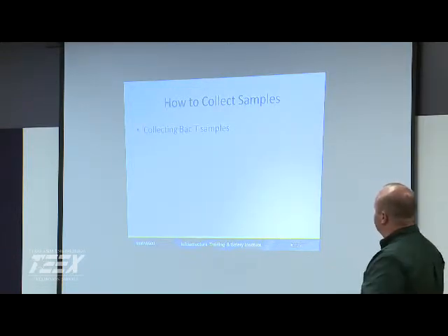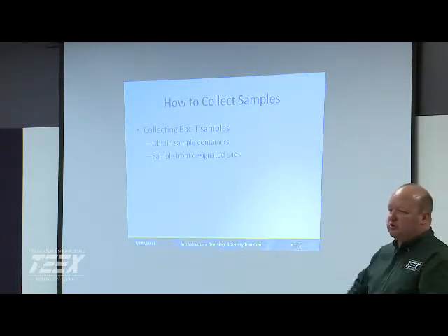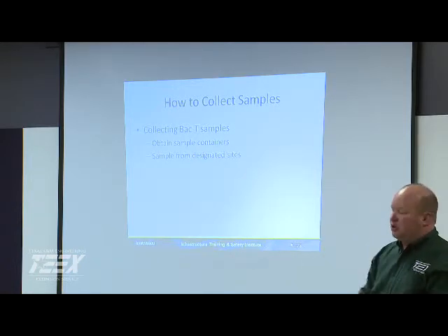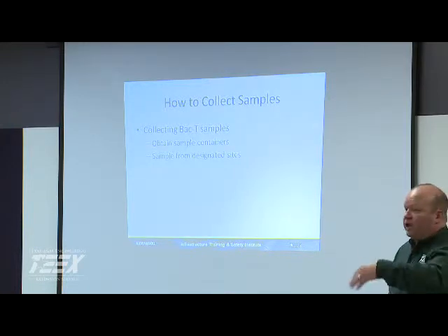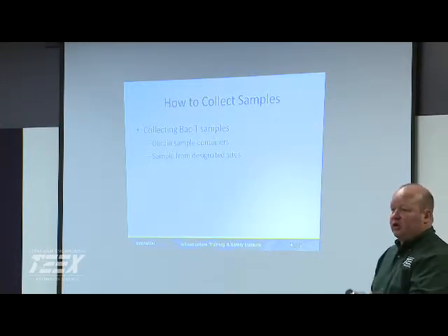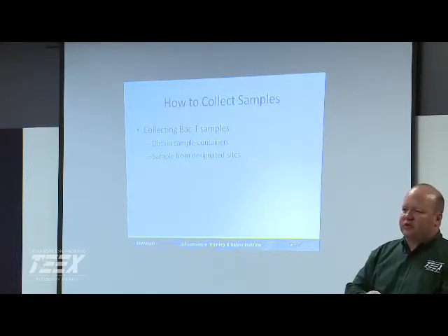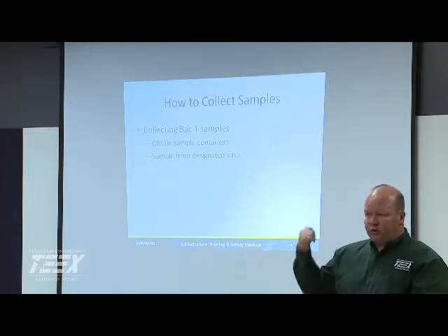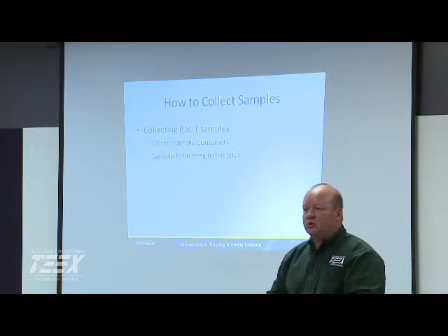Collecting samples: how do we collect our bacteriological samples? We need to make sure that we have appropriate sample containers. Y'all are getting them, you buy them, right? Sterile, and it has your sodium thiosulfate in it already. We need to make sure that we know how to pull the right sample, how to flush, how long you flush before you sample, and pulling your chlorine residual. How long do y'all flush? It all depends. Are you talking about for a repair or just? No, for your bacteriological samples, if you're going out to pull your samples. They usually flush about 15 minutes to half an hour.